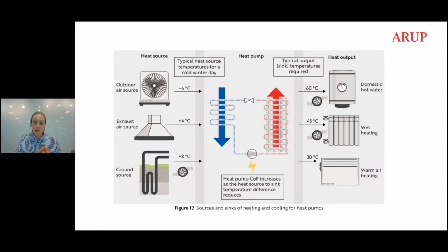So once we've gone through the section of what are your loads and how do you define them, we have a section about what technology you're going to choose to meet those loads. And as Mike discussed, we've made the assumption that by reading this document, you've made the decision to use a heat pump, but there are a lot of different kinds of heat pumps, and you might use heat pumps in conjunction with another kind of heat pump or with another solution as well, depending on what restrictions you might have for your development. So we have a section that discusses different heat sources, different refrigerants, different performance characteristics, and why you might make the decision based on the loads that you've defined to use a particular technology.